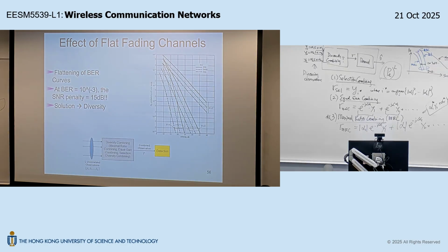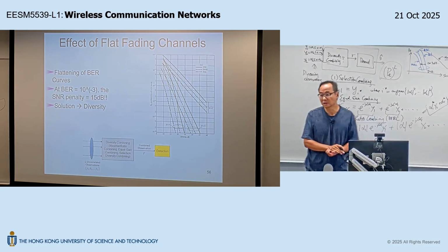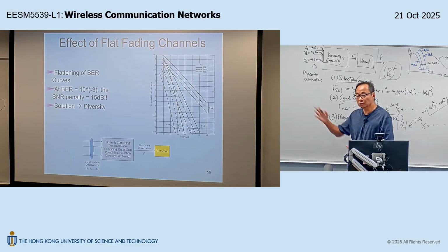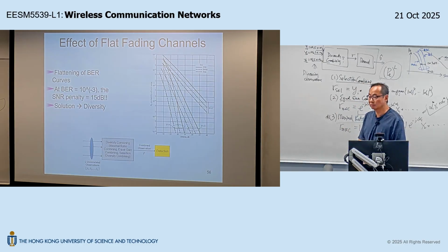If you need Y1 and Y2 in the analog domain, that means you also need two RF chips to generate the Y1 and Y2 baseband analog signals. So that means if you compute the MRC here, you naturally would need the full RF and ADC chain for each of these antennas. And then you need to pay 5 cost units. And that solution will not fly, will not sell.